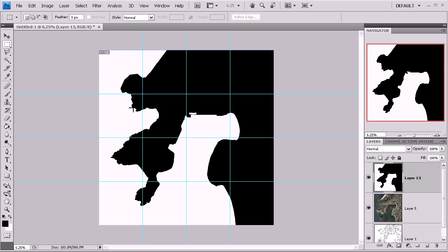And we're going to take a faster route, which is using a bit of a web designer's kit. So we're going to be creating individual slices for each one of these 16 squares just to speed up the saving process. Since we can come back and make edits on it, and then we can just immediately save out each of these 16 squares. Now you'll see that I've used the slice tool, and we just go square by square, making each of these squares an individual slice.